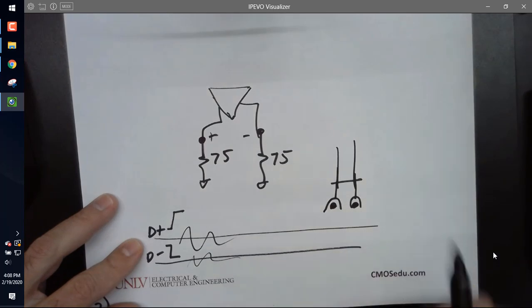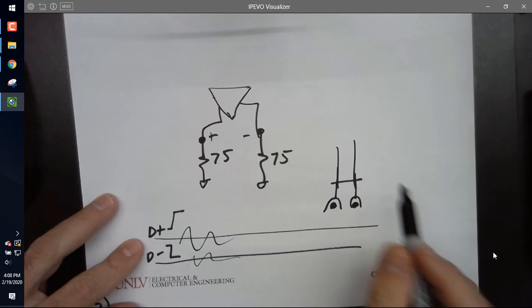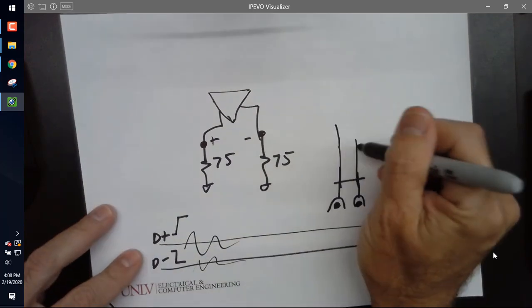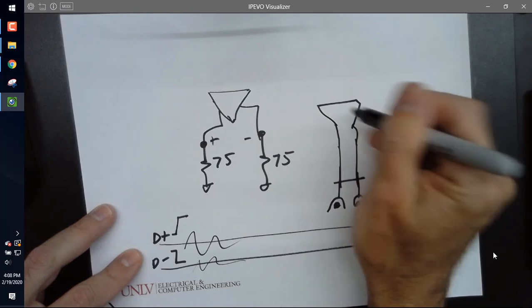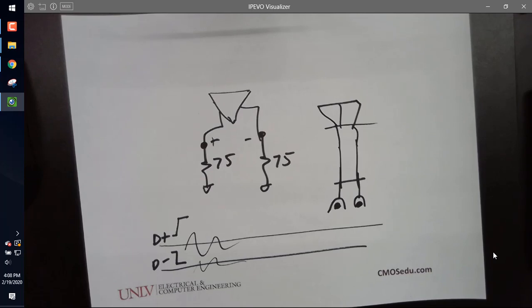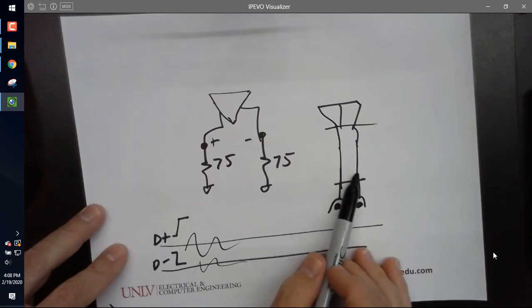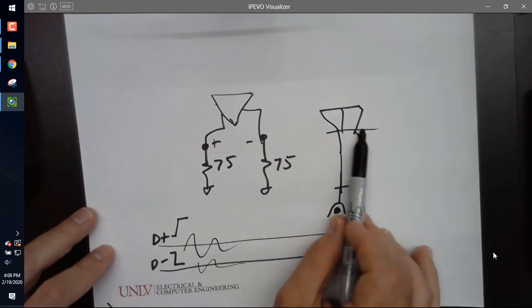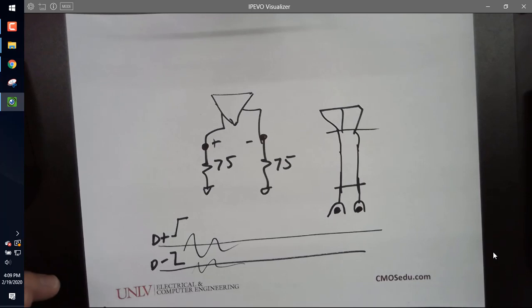It's this flat piece of cable that went into the TV. It was a rigid plastic, and it would go all the way up to the antenna. The antenna would be picking up and tuned to send radio signals down to your receiver, and then it was spaced out evenly like this, so hopefully the same unwanted signals would get picked up, and only the different signal picked up by the antenna would be amplified by the TV, okay?